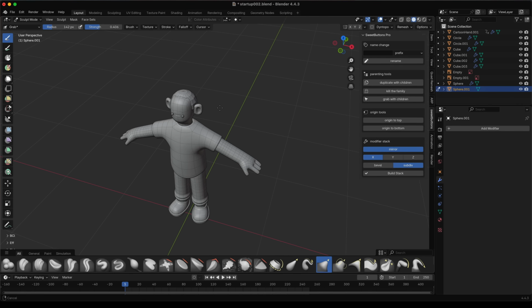It's the same general principle to sculpt the hair that we used to sculpt the head, but this time we're going to use remeshing as we go to add more geometry and be able to push and pull things. We might even use a couple different brushes. In this first one, only focus on using the grab brush and the smooth brush. That way you can get oriented with sculpting and it doesn't become overwhelming.